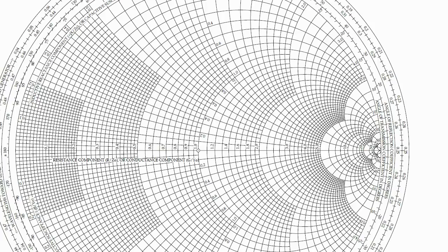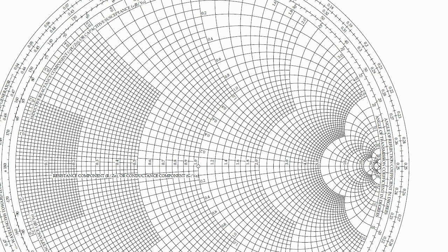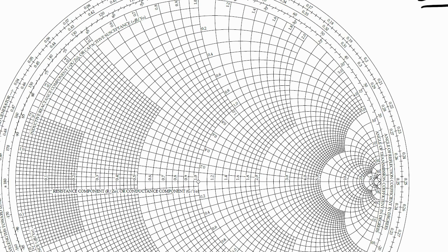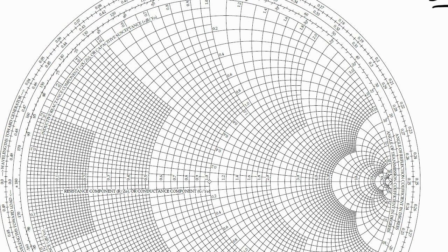So the first step is to plot the impedance point, the load impedance point. My normalized load impedance, remember, is 0.3 plus j 0.3. So this is my r equals 0.3 circle, and it intersects the x equals plus 0.3 circle right at that point right there. So this is ZL, and then drawing a vector from the origin to that point gives me my gamma L.